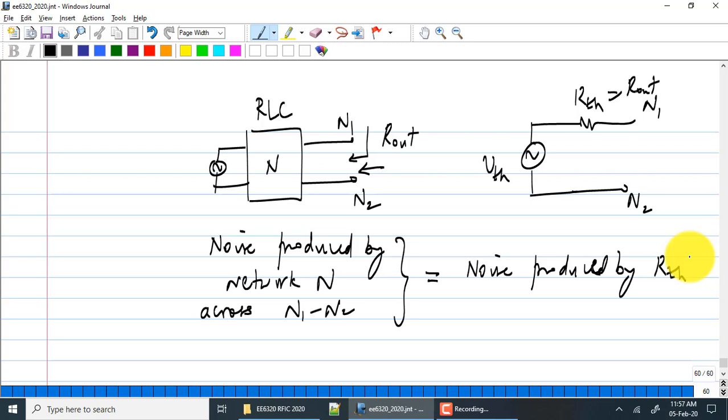So our problem is we need to find a way to create an input impedance of 50 ohms while not using a 50 ohm resistance at the input. So that's our job for the next couple of classes. There are also a couple of other things we need to learn. For example, noise factor of passive lossy networks, as well as noise of a MOSFET itself. We have been assuming 8kT by 3gm. Some slight modifications, we'll do that in the next class.